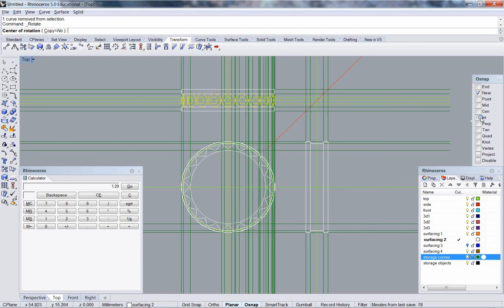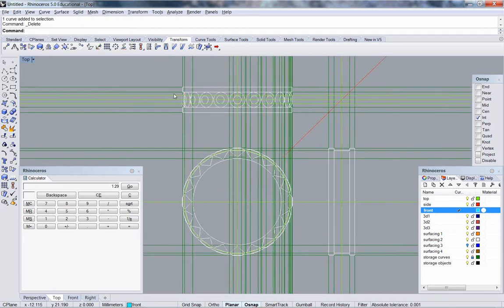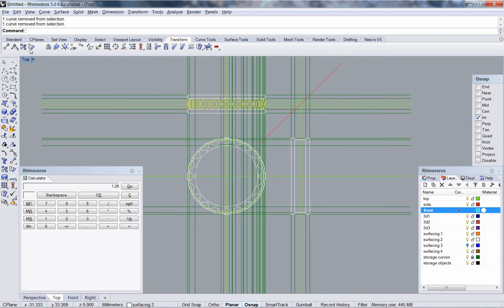This only is going to work because these are equidistant from the center. If you're ever wondering what a rotate's going to do, you can draw a circle, charting its path. And you can see how this circle passes through here to here. So, because these are equidistant from the center, it'll work. Otherwise, it would not. Okay? So, select my stones, take out the rims, rotate.